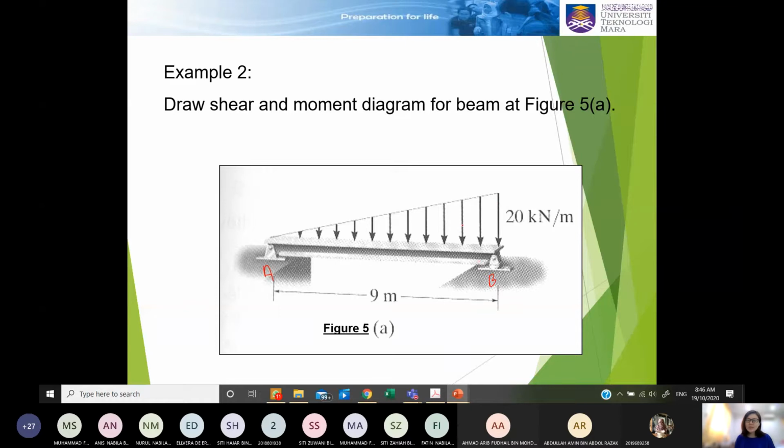But this loading is linear. I mean, you can see that it is proportionate, directly and gradually increasing, and it comes from one slope. Therefore, you will only have one equation along this A to B. You do not need to cut each section, because this loading can be described with one equation,